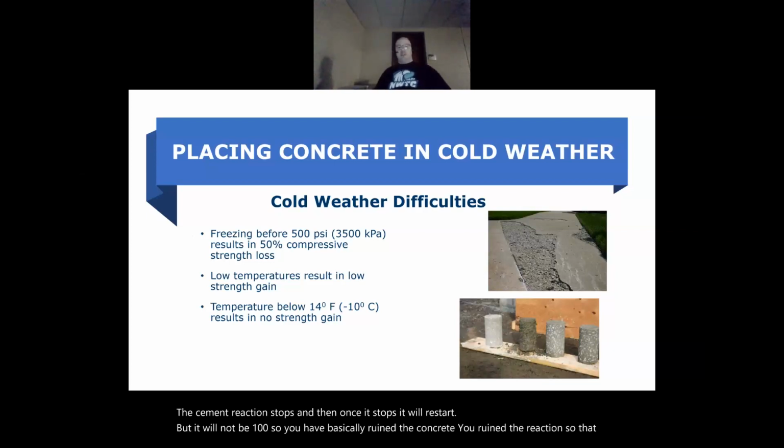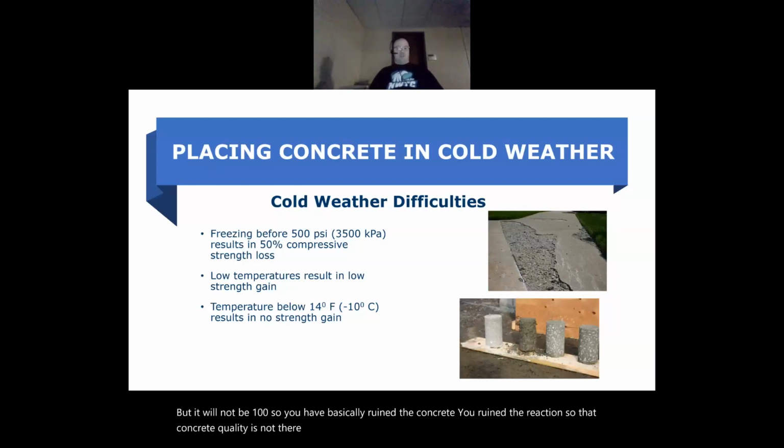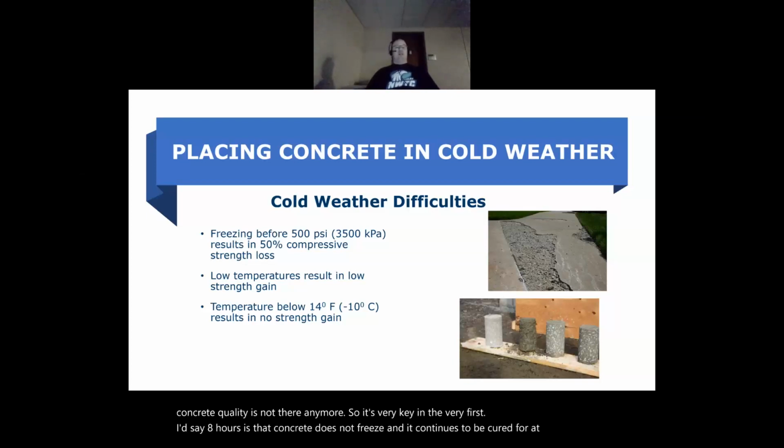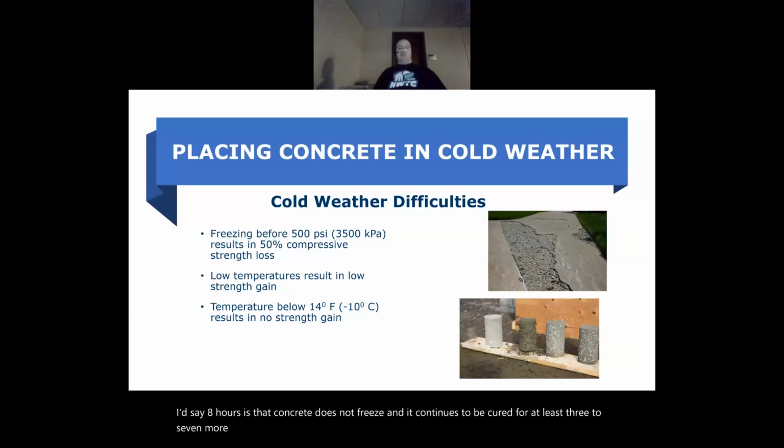It's key in the very first 8 hours that the concrete does not freeze, and that it continues to be cured for at least 3 to 7 more days to make sure hydration continues with heat, time, and moisture.